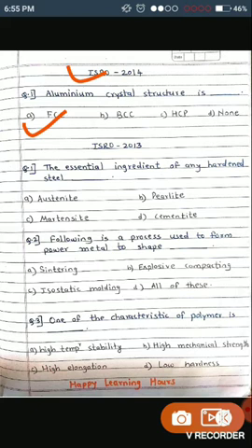The next question is, let us see which questions have been asked in ISRO 2013. Now the first question: the essential ingredient of any hardened steel is. Now we know it's martensite. Okay, martensite, it's the hardest phase. So let's say you have heated steel, and if you go for very rapid quenching, very fast cooling, then chances are that martensite phase may form. Such type of steel has very good hardness.